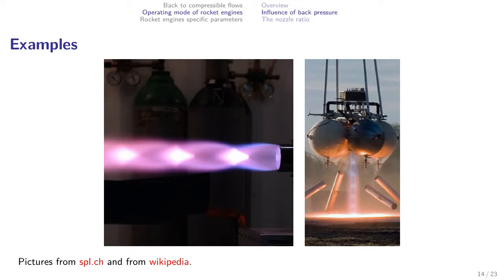Before, the pressure is higher at the outlet, okay? And when you reach this point and you go beyond it, the pressure will be lower than this, and so you will be in an overexpanded situation. The only way to maintain this would be to change the geometry of the nozzle in real time, but it's really complicated because these systems are subjected to really high constraints of pressure and temperature, and making this kind of geometry variable is complicated to design.